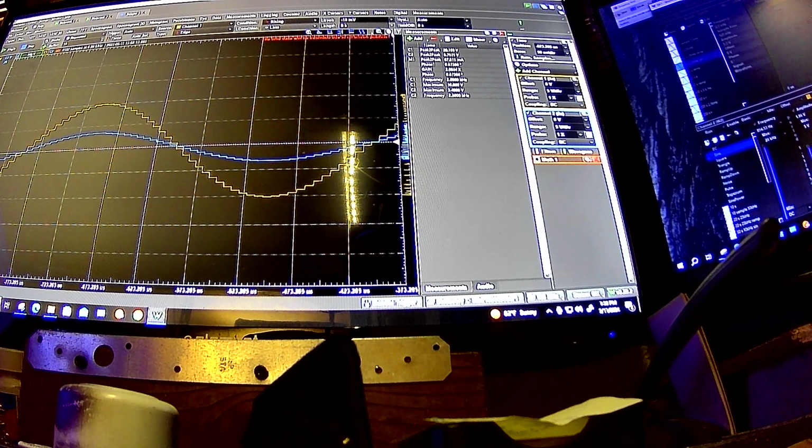So unless you can do tricks like Analog Discovery did and apparently vary their analog reference, so they can maintain the resolution better, then you're kind of screwed there too, as well as the frequency limits. Because like I said, if you set it to like 200 samples, you've got 200 samples per cycle. That's why you're stuck at 2.5 kilohertz here.